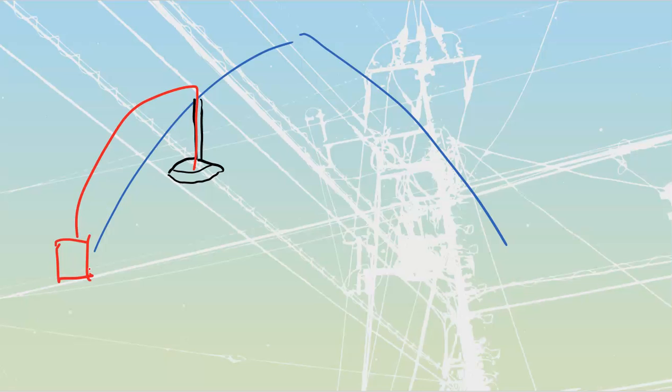And then the last place that we commonly see it is inside of churches or places of worship where they want to have a quiet environment, so they want to remove that ballast noise. Any one of those installations is going to require that remote mounted ballast. You are usually going to have to go to a higher voltage rating. Usually it's going to be 1,000 volt rated conductors that you're going to have to run from location to location, because it's a much more intense voltage that we'll use for striking a lot of our fluorescents.